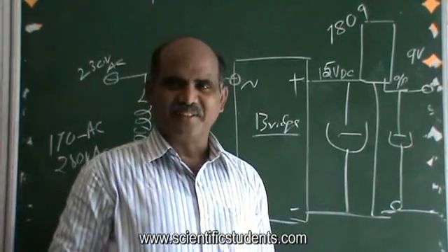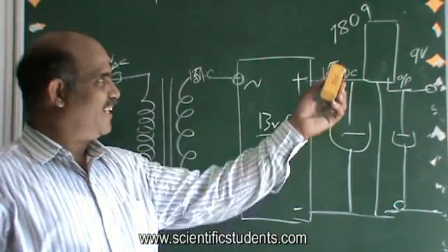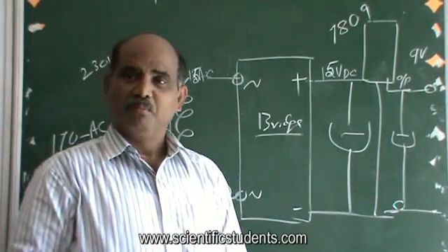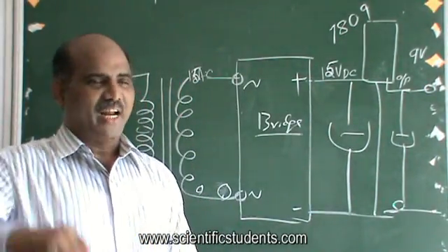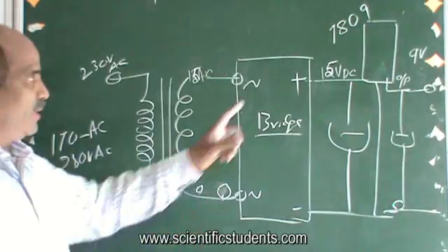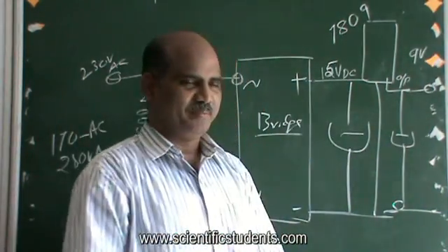So that is an interesting regulator IC, very low cost. I think it's around 12 rupees or something like that, 15 rupees max. But still it does a lot of activity. Right from your input of 170 to 260, whatever it is, your output voltage is 9 volts constant.